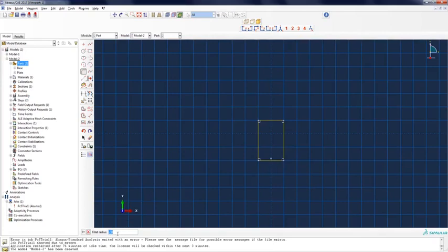Here we need to fill in the fillet radius. Ideally we want to use something different, but smaller maybe. But we can try with 2 first to see how it works, see if it improves. So we first click on the entity near the end to be filleted, and then we click here. Here we have a radius.